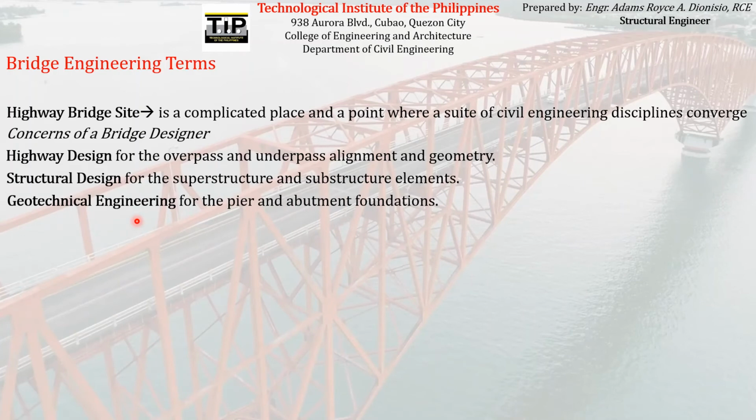Another concern of a bridge designer is the geotechnical engineering for the pier and abutment foundations. Not only the structural design of the superstructure and substructure is the concern of the bridge designer. The designer must also engineer the supporting soil that will support the whole bridge.